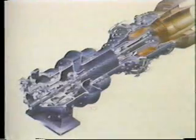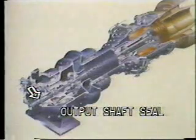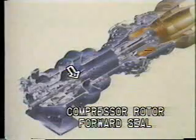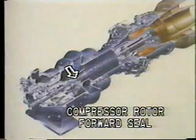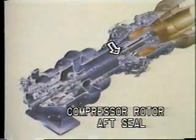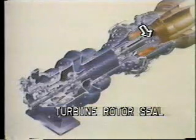The turbine engine has 4 labyrinth seals operating on pressurized air. The first seal, located near the cold end of the engine gearbox, is the output shaft seal. The second seal is the compressor rotor forward seal. The third seal is the compressor rotor aft seal. And the fourth seal is the turbine rotor seal.